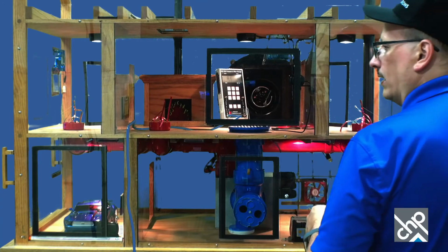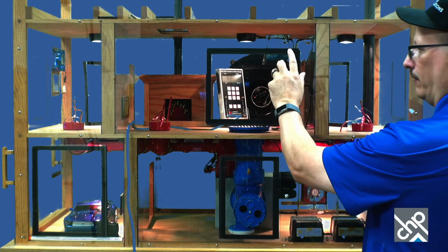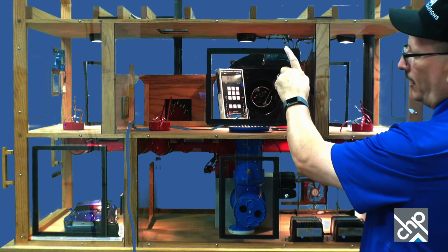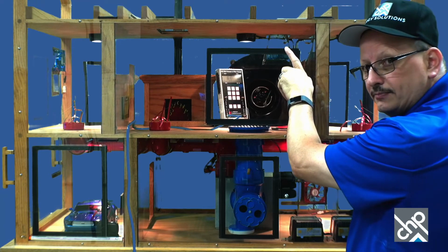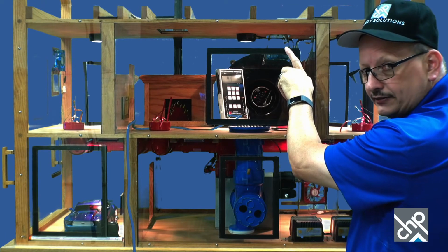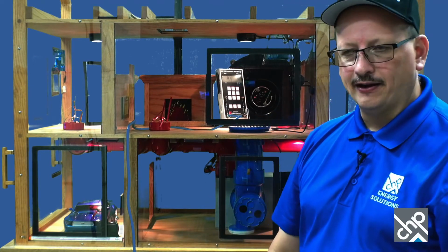So what I'm going to do first is turn on the exhaust fans, what we call small fans. Some people call them the exhaust fans, like kitchen, bathroom, dryers, and then the air handler, sometimes they'll call that the big fan. What you don't want to turn on, though, is the really big fan, which is the whole house fan if they have one in the hallway, and of course the blower door is not on. Those are always going to cause a huge negative pressure if you've got everything closed up. So you're just using the exhaust fans and the air handler fans.